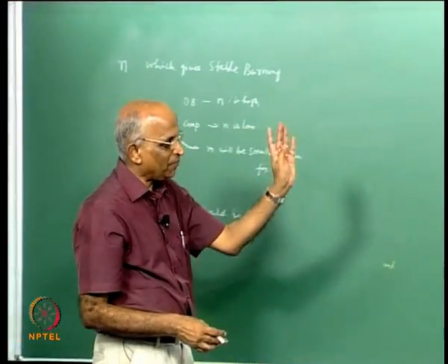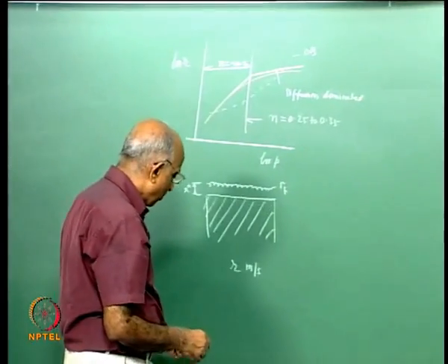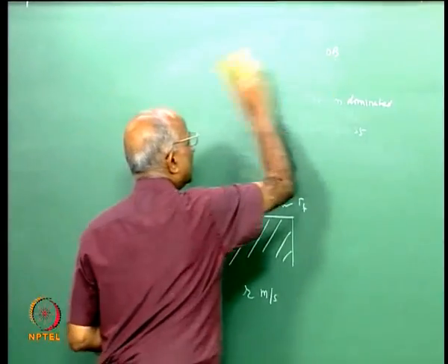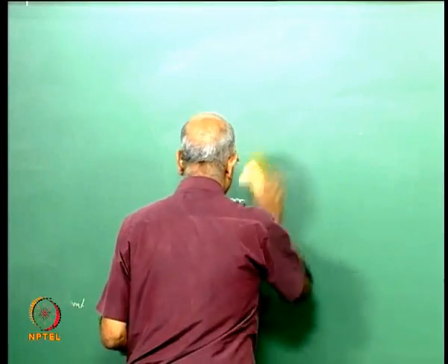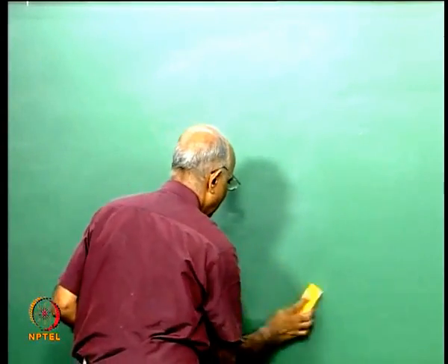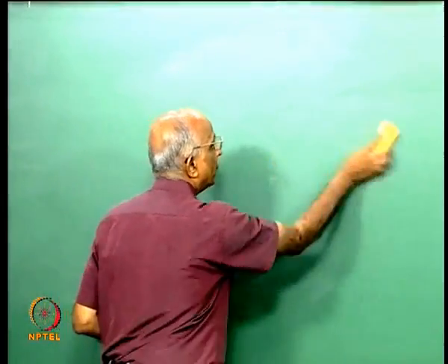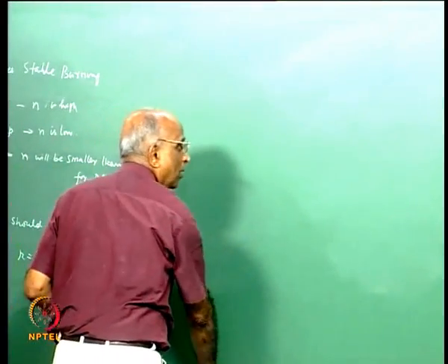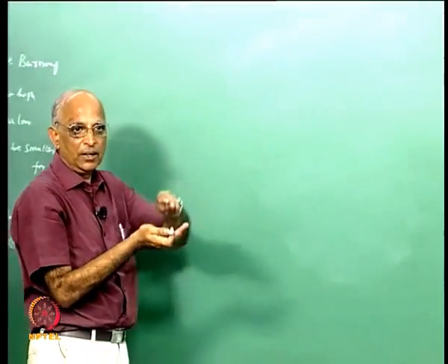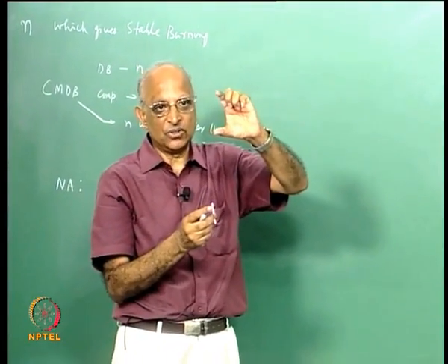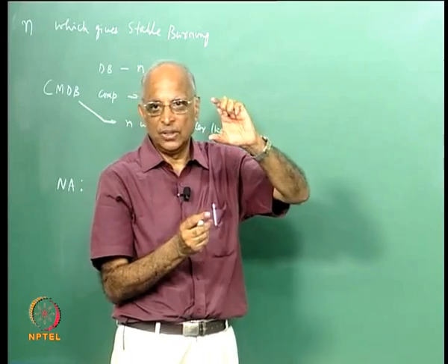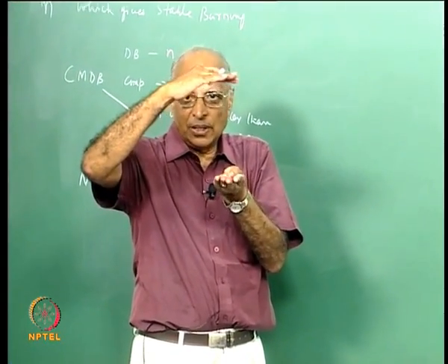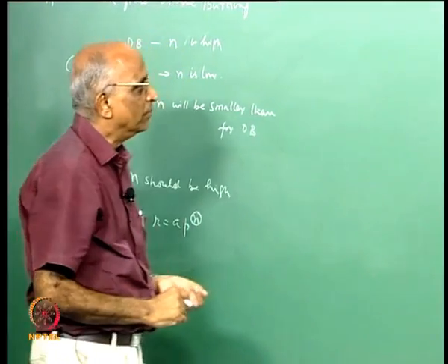I think let us keep it in mind, we should work out some numerical problems for burn rate and put things together. But what we have done is, for double base we looked at the evolving layers like the fizz zone, dark zone and also the second luminous zone, whereas for composites we use the simple Hermance model wherein we talk of a flame standing away from the surface by a standoff distance. We also know what this standoff means, right? When a gas comes it takes some time for things to chemically react and form a flame.